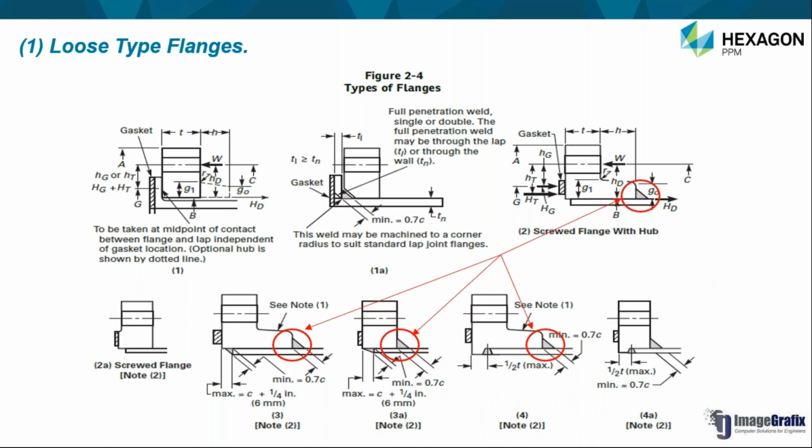So it is actually fabricated and directly welded to the nozzle. That's why the outside there is one fillet, and the flange should also give some relieving chamfer so that it should not interfere with your outer fillet when the flange joint is going to be tightened. Okay. Now if you observe figure number 2, it is basically the joint between your flange and the nozzle